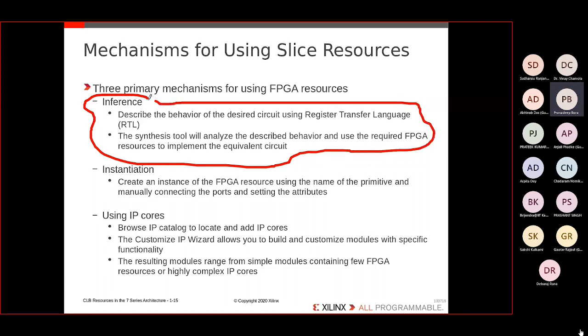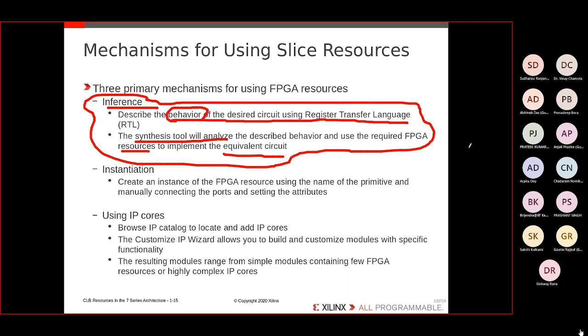What do you mean by inference is, I'm writing the behavior of the desired circuit using RTL language, that is register transfer level language, right? That is Verilog or VHDL or SystemVerilog, anything you can use. But what you need to do, you need to describe the behavior here. Depending upon the behavior, the synthesis tool will analyze. That means it will infer and it will use the equivalent circuit using the FPGA resources.